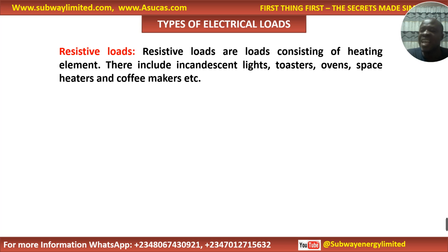So those electrical loads that consist of resistive elements are called resistive loads. They consume lots of power. If you run resistive loads with your system, that means you want to destroy your battery as fast as possible, except you run them during peak sun hours and during daytime. That is the best time to run resistive loads.